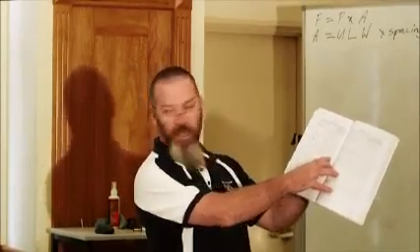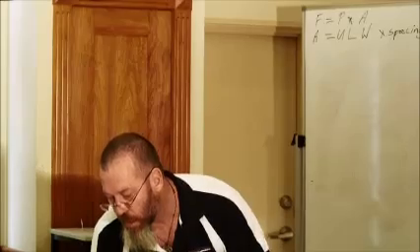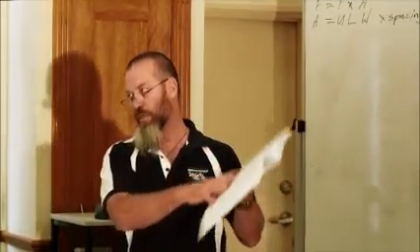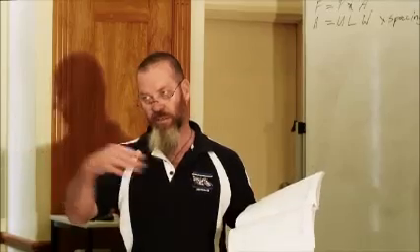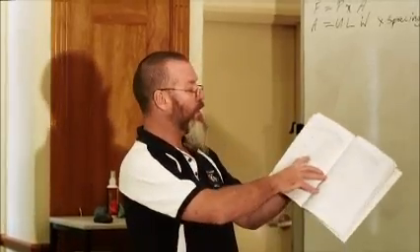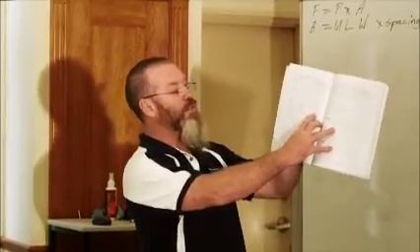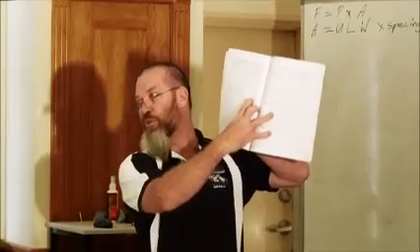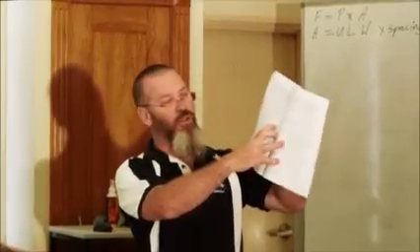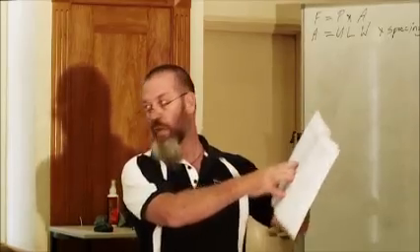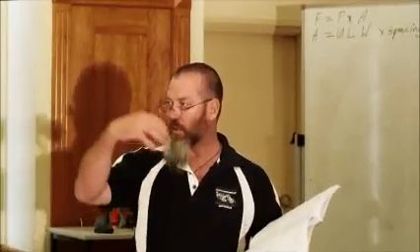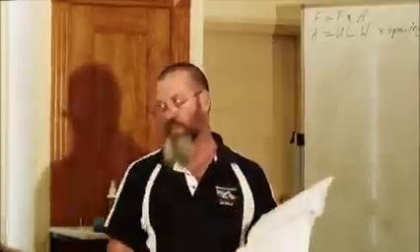So you come down here, huh? 2006 doesn't say, it says nails. Yeah, it says nails in the old standard, but it's screws in the new standard. This is mistakes, I told you. It was a pretty average document. So you've got to come down, and you'll see that 175 by 3.05 deformed shank nail is suitable for that 0.29 of a kilonewton resistance. So that's what it's all about. There's all these alternatives inside these tables.